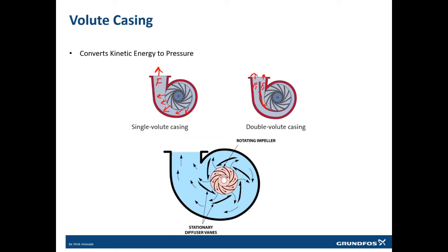This will help to divide the radial forces on the pump. Earlier the total flow was giving the radial forces to the pump. Now this force is different than this force, and this will not make any additional forces on the impeller. So all the forces in between will be taken care of by this additional partition.